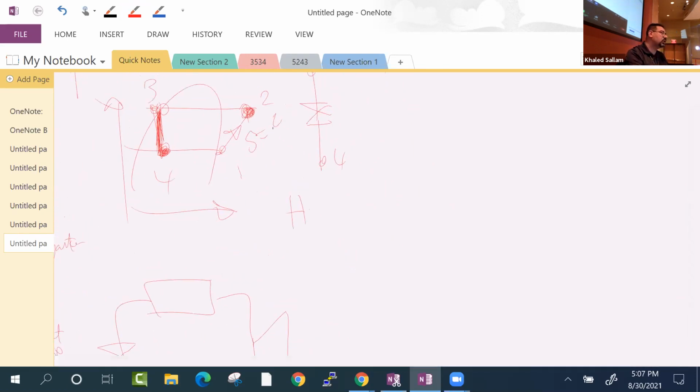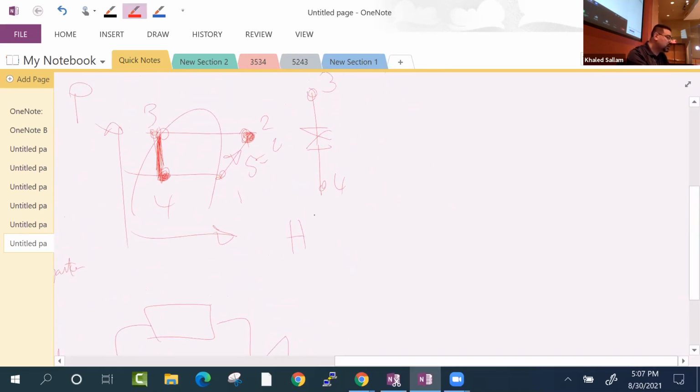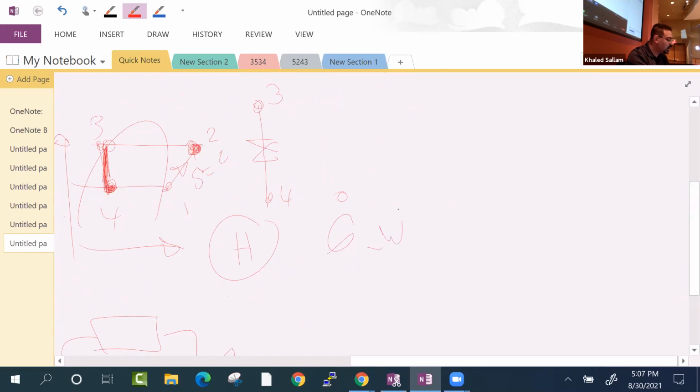Which is constant H, right? So it's constant H. Why? Because if you apply the first law to that throttling device, Q minus W equals m dot delta H. How much work in the throttling device? And how much heat transfer? Zero, because it happens so quickly. So it's really just constant H. So whatever H at 3, it's exactly the H at 4.